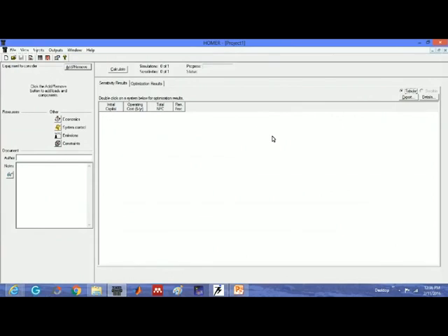Suppose you have this AC load and all 20 kilowatt is load, so at least you need a 20 kilowatt converter, taking into account the efficiency of the converter, let's say 80%, 90%. So the size of the converter will be greater than the total demand. Suppose you have DC available and you want to feed 20 kilowatt of AC. The size of the converter will obviously be greater than 20, right?